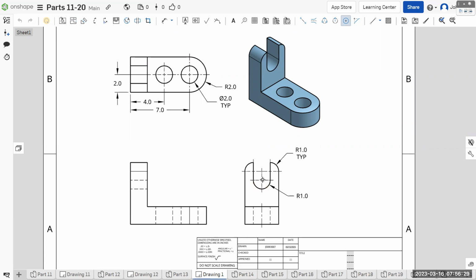And then the only curved surfaces left are over here, where the height from there to there gives us the height location, and the width, which is side to side. It's debatable whether it would be better down here or up here. I guess up here, because it crosses over fewer lines that way. So for this center mark, we have its vertical and horizontal direction on the view.